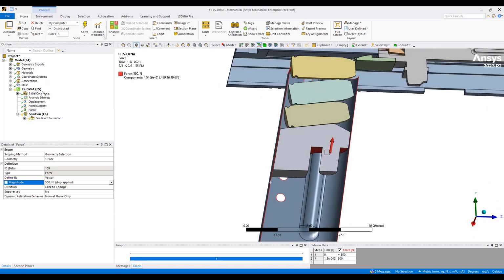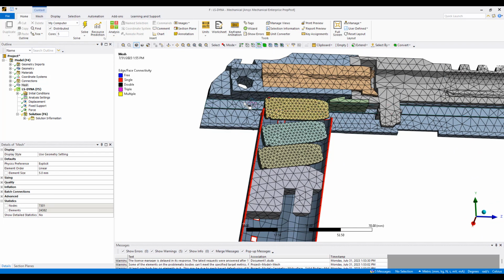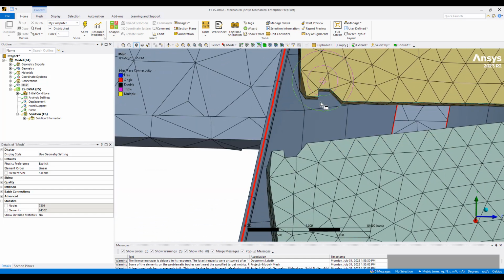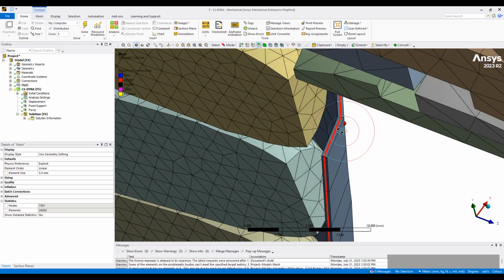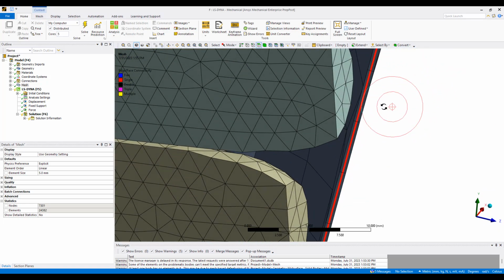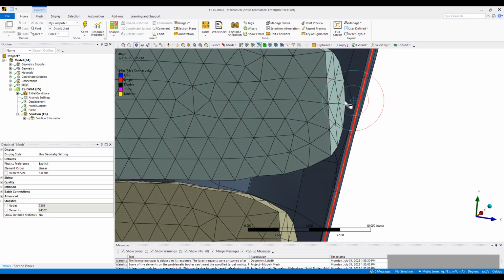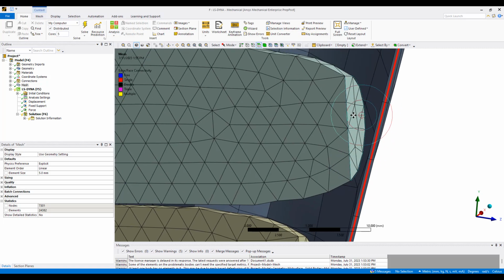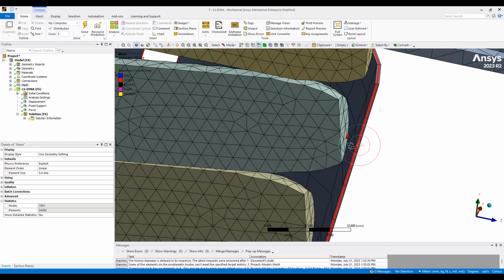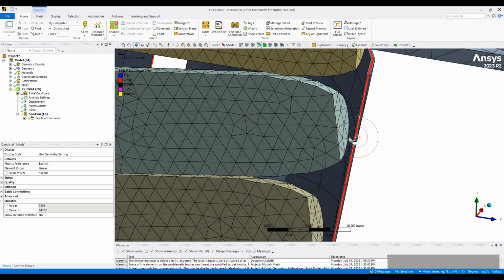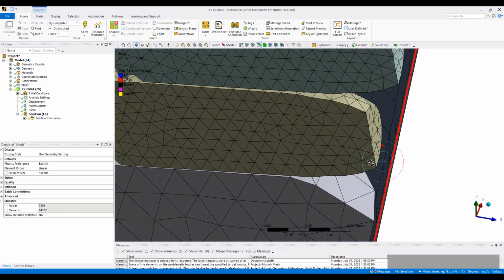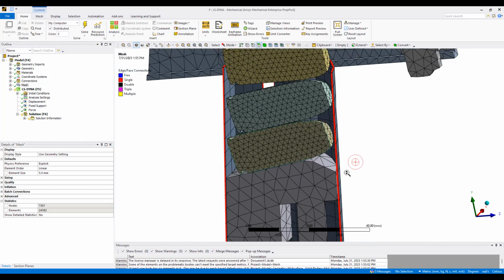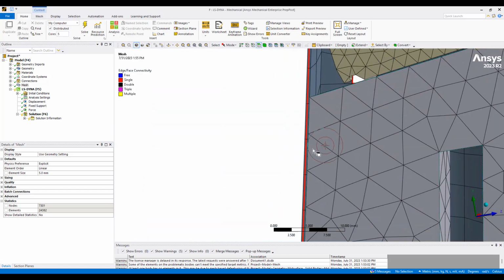One of the things that's interesting with LS-DYNA is that we do take into account the thickness of the mid surface, and you can see this is the mid surface here. Sometimes we have to be careful with the mesh. The reason I refine my bullets is that if the mesh is too coarse, sometimes it'll be jagged and poke into my mid surface, and that'll cause simulation issues where things won't move properly.